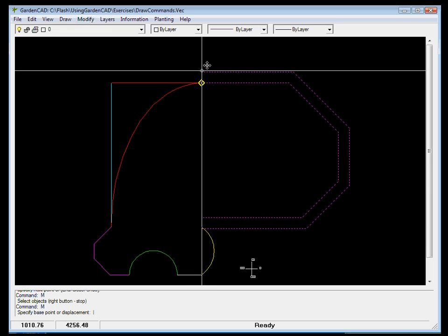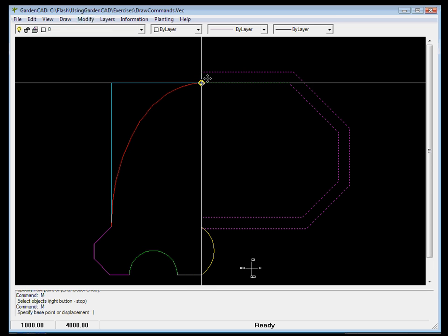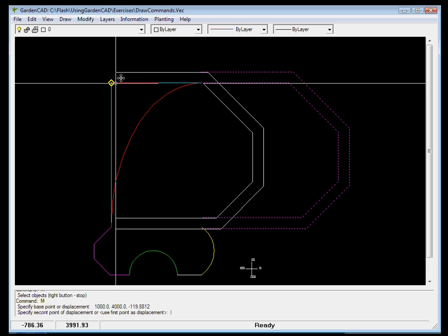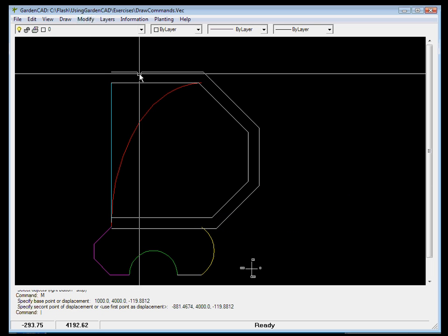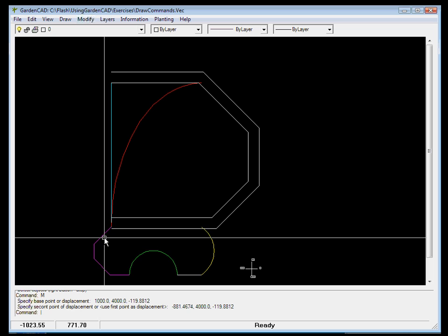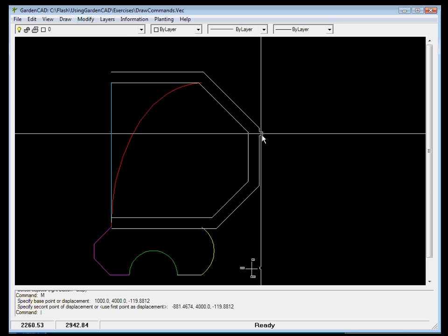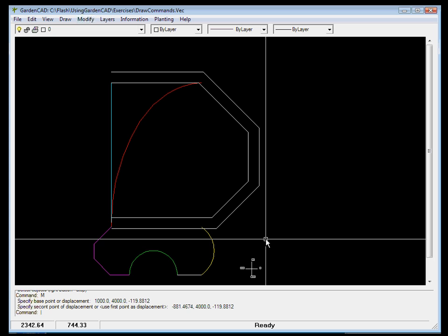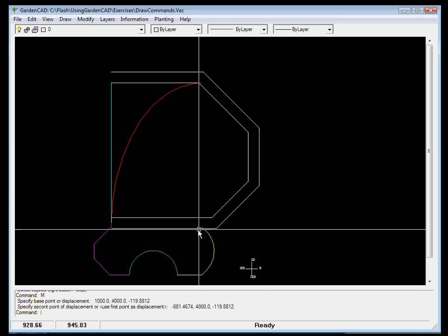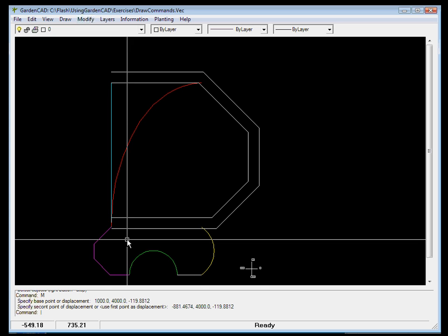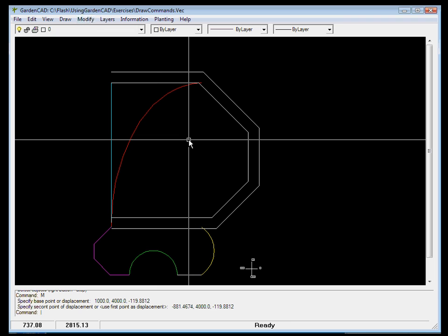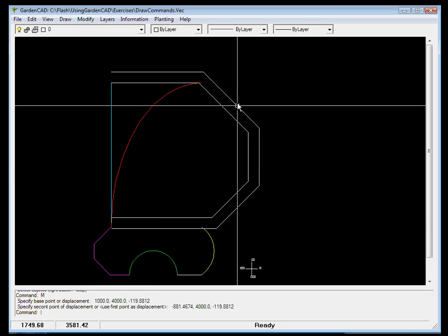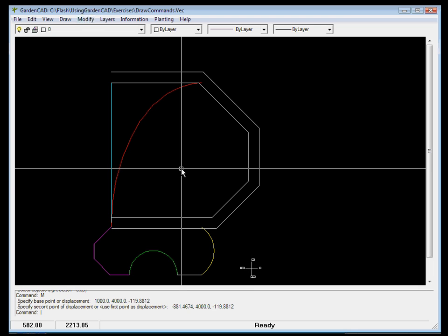that point there. You notice I can't find this point, and so there's my point. If I wanted to, I could then move it to that position there. So our masonry wall now starts at that point there, goes around through there, and is locked into position. There's just a little bit of trimming to do. We might even, that would not make a lot of sense, would it, with a masonry wall coming up in this direction. I'm sure you get my drift. We're just trying to show you the multi-line command, but it's a very powerful and quick way of drawing walling and paths.